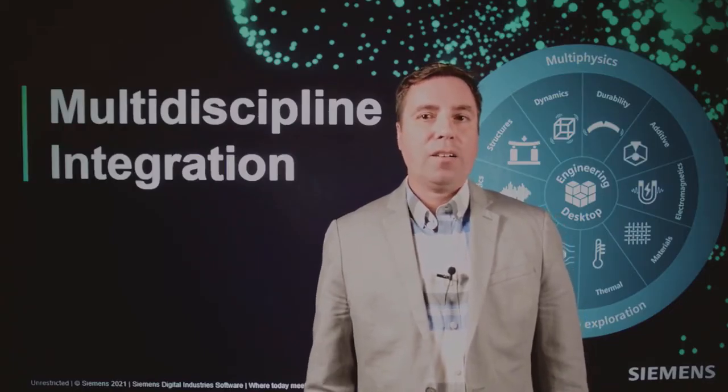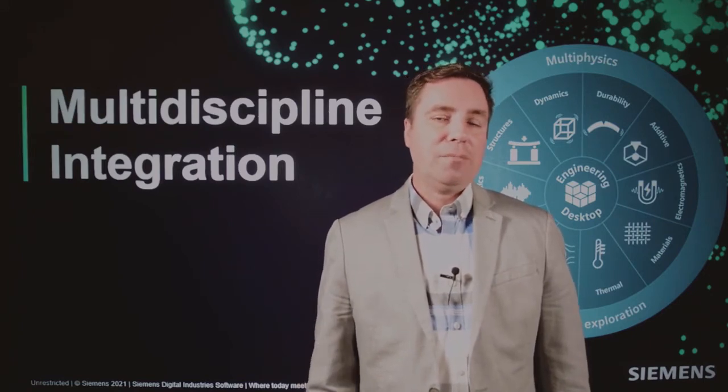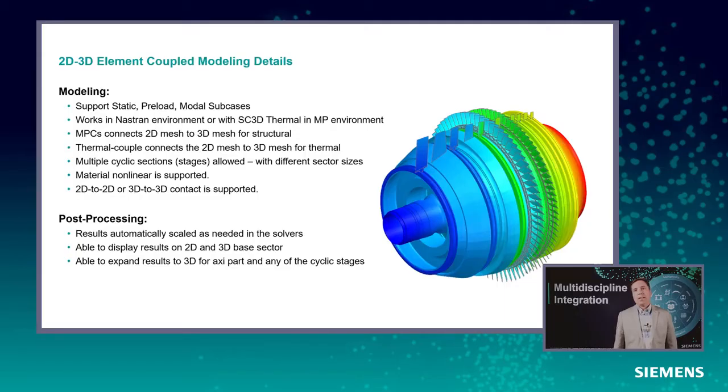The same property scaling for 2D, 3D coupled models has also been implemented in Simcenter 3D Thermal. It's thus possible to use the 2D, 3D coupled model in either a structure-only Simcenter Nastran model, a thermal-only Simcenter 3D thermal model, or a co-simulation of Simcenter Nastran and Simcenter 3D thermal model in the Simcenter 3D multiphysics environment.